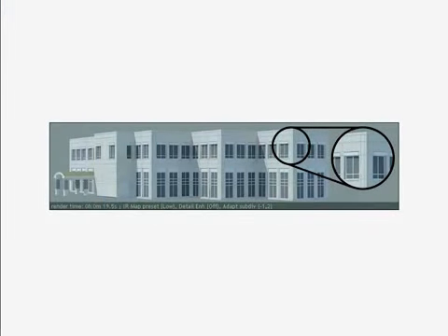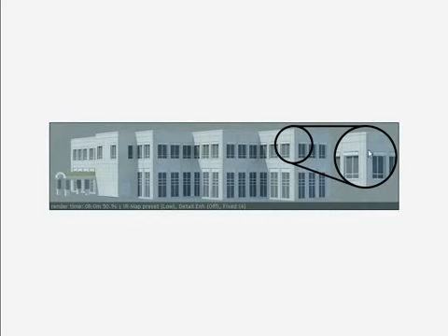This is what it looked like before, and I'm just showing this again to show what it looks like right now. And if we change the image sampler to fixed and change the subdivision value to 4, this means that each pixel will be subdivided 4 times horizontally and vertically, thereby giving 16 subpixel samples. And the improvement is pretty drastic. Notice that when I render this again, the render time increased approximately 2.5 times, but you see a lot more detail brought out in the Radiance map.